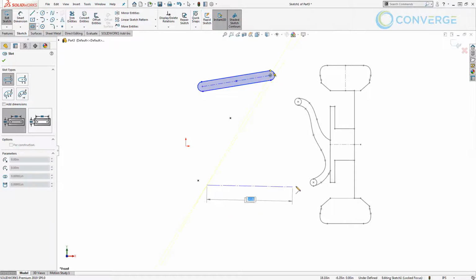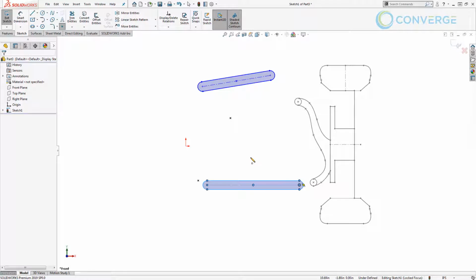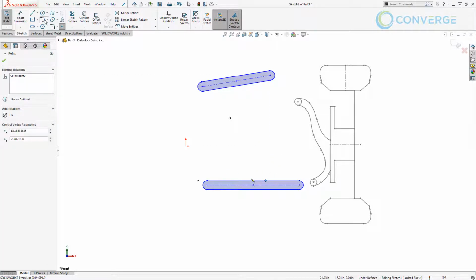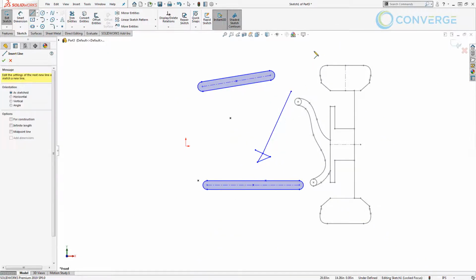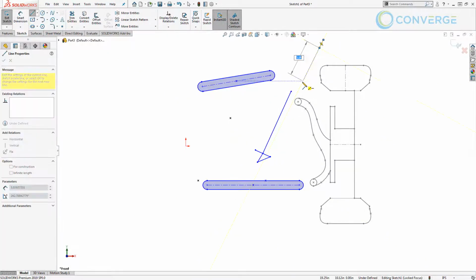We could get a little bit more complicated and add things like pickup points for suspension if we want to know exactly shock travel, things of that nature. So for example, on this lower link, which likely would contain the shock and the suspension members, we could put a point here, and then we could create a shock itself with just a basic representation. Again, we will just create some lines here. We'll carry these up, double click, and we'll do the same thing on the top. We'll create a couple lines, and then we'll draw another member here.